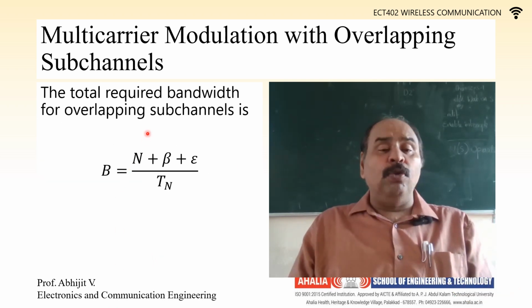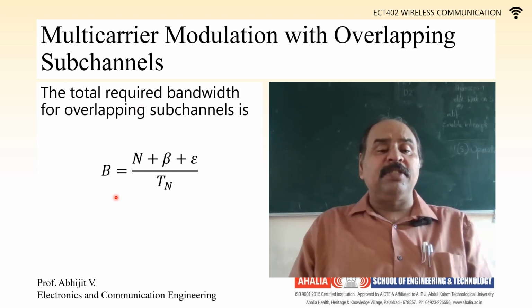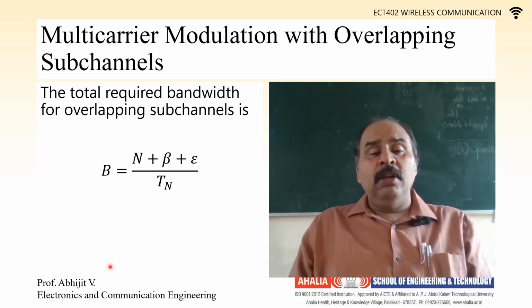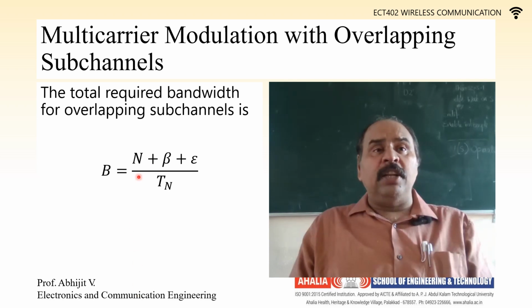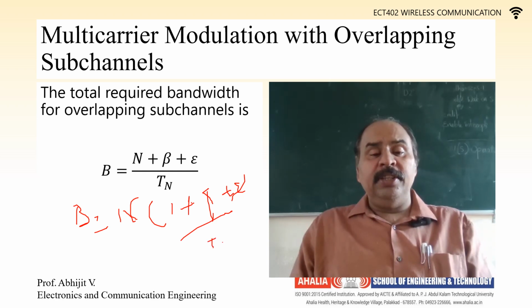Now, in case of overlapping channels, the total bandwidth is defined as B is equal to (n plus beta plus epsilon) by Tn. In non-overlapping channels, how was it defined? It was defined as B is equal to n into (1 plus beta plus epsilon) by Tn.